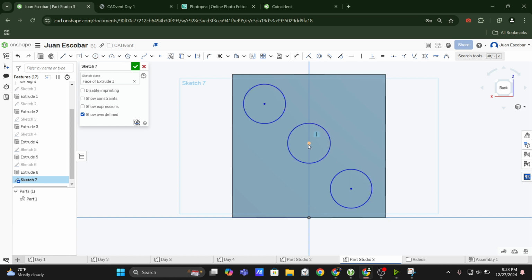But let's say you didn't want it to be vertical from the origin. Because sometimes you want to add something, but it auto constrains it, and it's not an auto constraint that you want. So let's say I'm just out here in space and see, oh, it's adding a horizontal constraint from the origin. Let's say I didn't want that. To disable auto constraints as you're drawing something, you can press Shift. And now it'll get rid of that auto constraint. So now no auto constraints will pop up because I'm holding down my left Shift key.